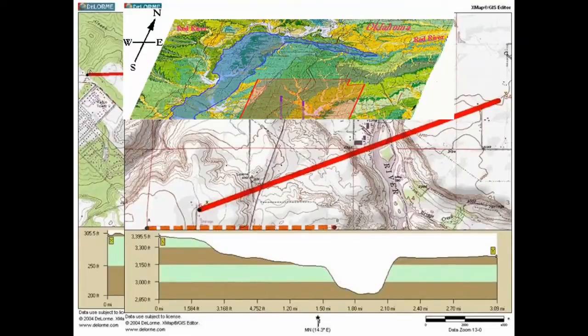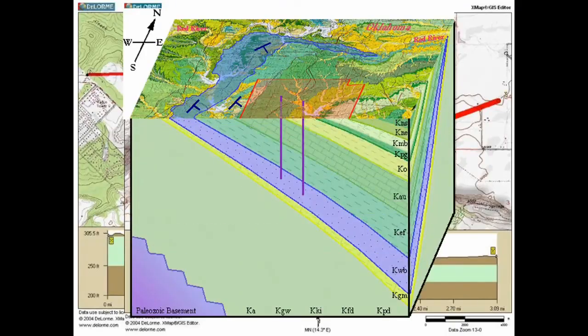What about a topographic map that also has some geology on it, like this one? Could we see what the subsurface looks like? Well, it is great if we had a few strike and dip symbols, like one here, one there, one here, and hopefully a few more that tells us in which way the layers are dipping. Well, after we have drawn all these, couldn't we do 2 cross sections and kind of put them together at the edge of my geologic topographic map? Well, that now gives us a beautiful picture of what the subsurface looks like.